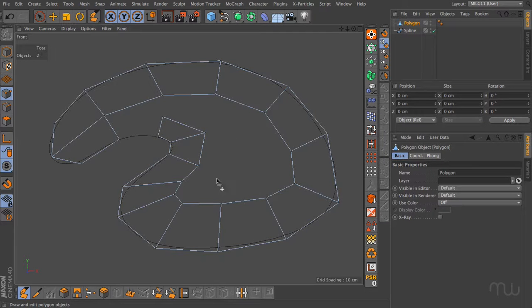Now when you're making shapes like this, you have to think about the fact that you have to fill this hole in, and we'd quite like to fill this hole in with some quads. Now I haven't been paying attention to my edge count, so I don't know if this is actually going to work yet, and I might have to end up cutting some more edges in, but we'll see how we get on. Now if I just copy another edge to here, now I can weld this point here. Now I also want my quads to be fairly evenly sized as well.